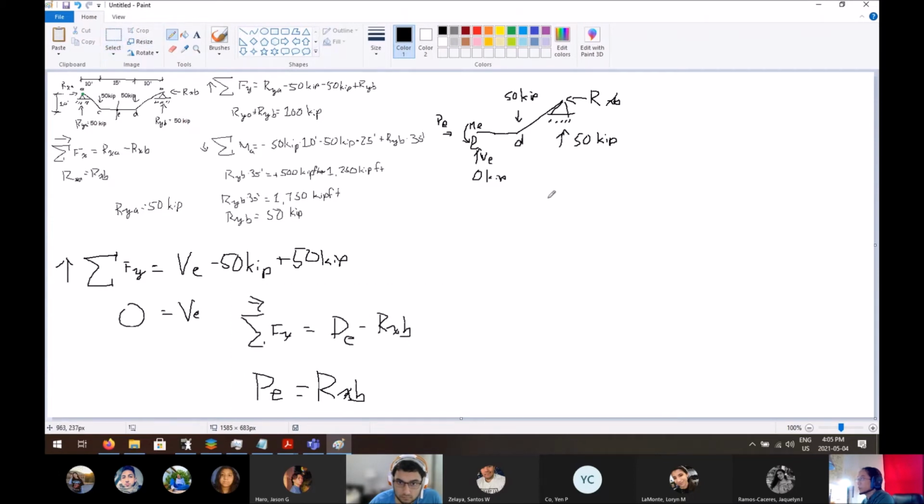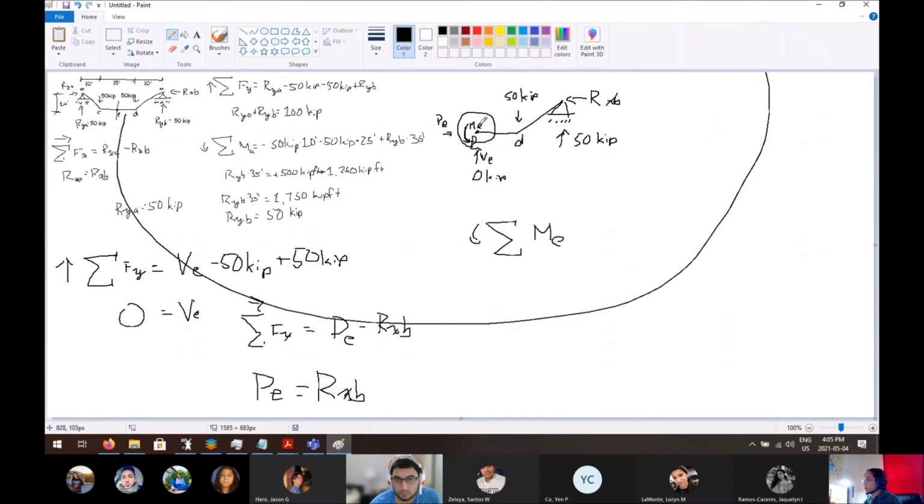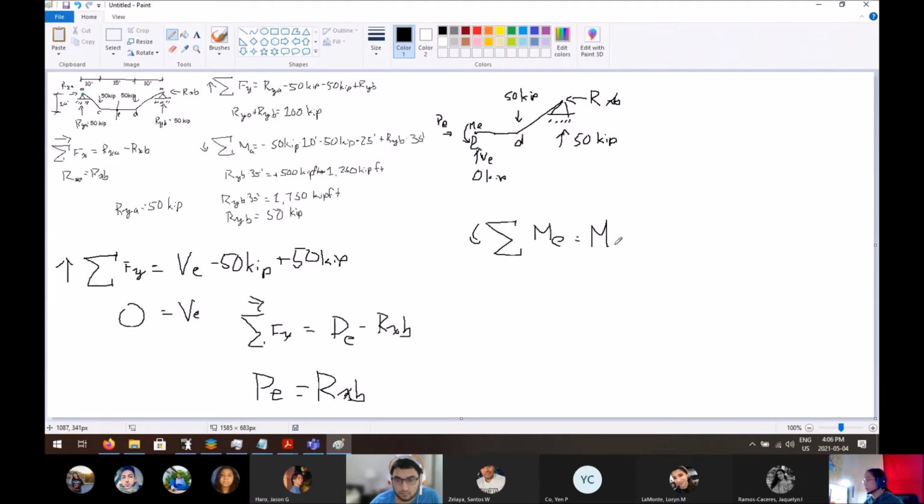Now we'll do summation of moments, right? That's the next step. Summation of moments at E. That's where we cut, and we already have a moment there. So a moment at one place doesn't apply to any other place. It only applies to this location right here, because the moment has to orbit around here. If it was a moment that was 1 foot away, or 100 feet away, it has to circulate around here. So whenever you're taking summation of moments and you are already given a moment, you have to include it.